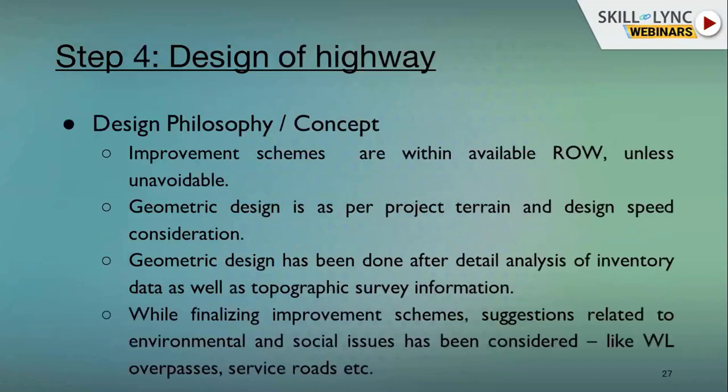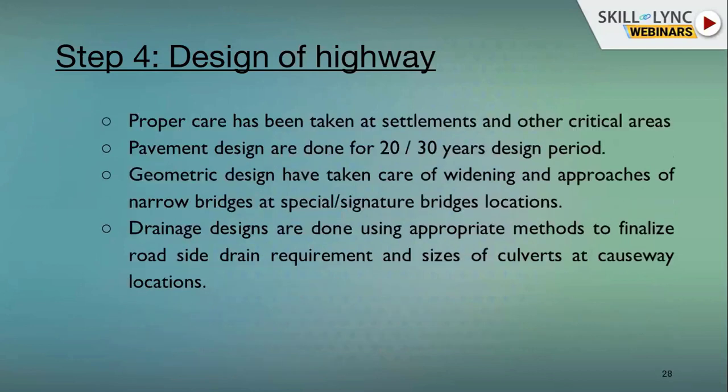Then comes the role of design of highway. Here, the role of the highway engineer will be very much needed, because he will finalize improvement schemes and geometric design as per terrain, based on topographic survey and inventory data. Also, he will cover in his improvement proposals how to tackle wildlife areas and environmentally sensitive areas, how service roads are to be provided and where. All those will be covered under design of highway. Then proper care is to be taken for settlement.